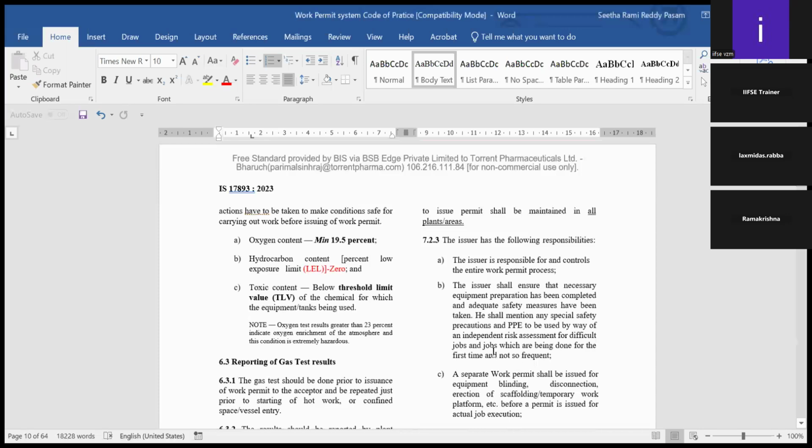Sir, before we enter this area, we take the permit, and we use the respiratory system, like SCBA, or it depends upon which type of industries provide PPEs. Then after that you can enter that area. Without PPE, no one can enter this area. This is a dangerous area. Correct. Until you do any testing, you will not understand, because those hazards are not visible.